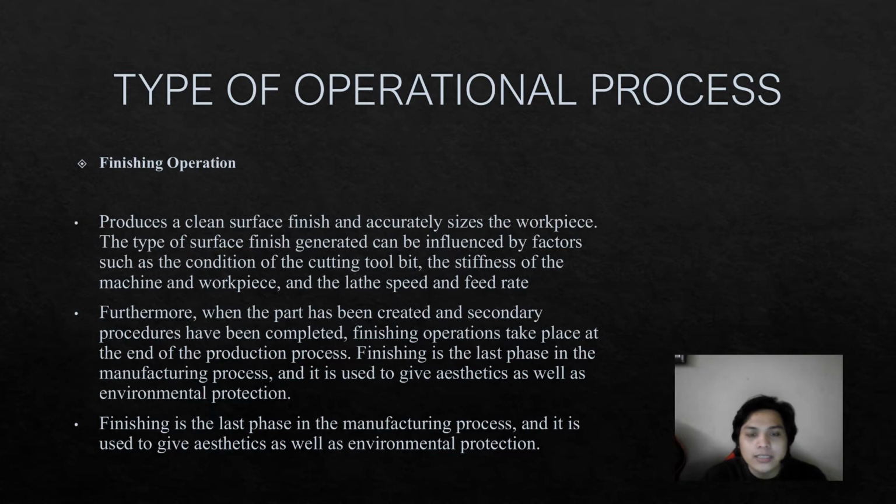So the finishing process produces a clean surface finish and accurately sizes the workpiece. The type of surface finish generated can be influenced by factors such as the condition of the cutting tool bed, the stiffness of the machine and workpiece, and the lathe speed and feed rate.